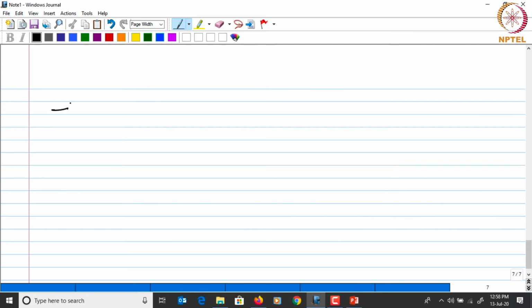So as I said, in this kind of alloying, a large portion of the sintering period is dominated by the homogenization process, and the densification continues after the homogenization has completed.